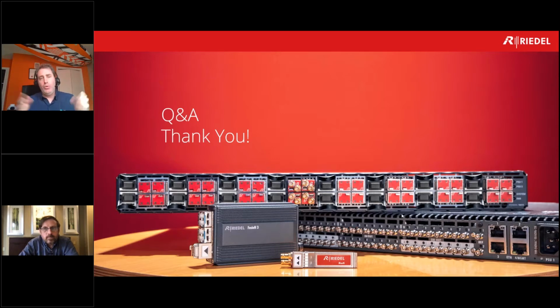And again, we learned that from different deployments we did. At the beginning, we thought it's kind of a perfect world when PTP and Blackburst are aligned. We soon realized it was not the case, so we added this frame sync inside. We also added all the 2022-7, so redundant paths A and B. And for JPEG XS and J2K, we're adding more buffer now to really cope with the jitter and features like that.